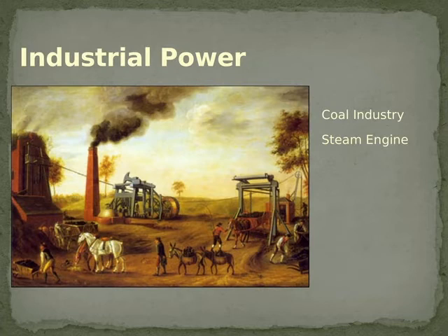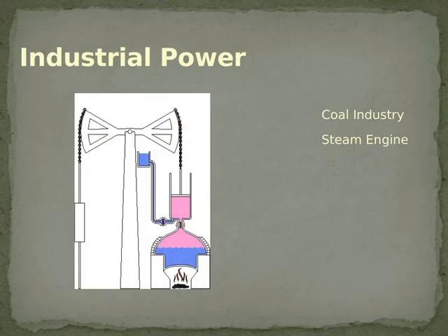And one of the alternatives they came up with was using a simple engine. And the engine would power a simple pump. Now, unfortunately, this pump is not animated. The particular program we're using here doesn't show it. But if you can imagine, you've got the boiler on the right here. And what the boiler will do is the boiler will push up a piston, right? So the steam will push up a piston, which will force the pump down.